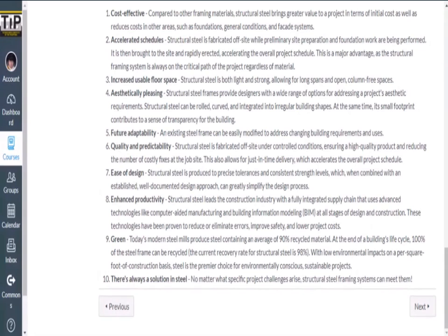So, for example, you cannot use reinforced concrete for bracing precisely because we know that concrete is strong in compression but weak in tension, and bracings may be subjected to either tension or compression. So meaning concrete is not a good choice for bracing systems.